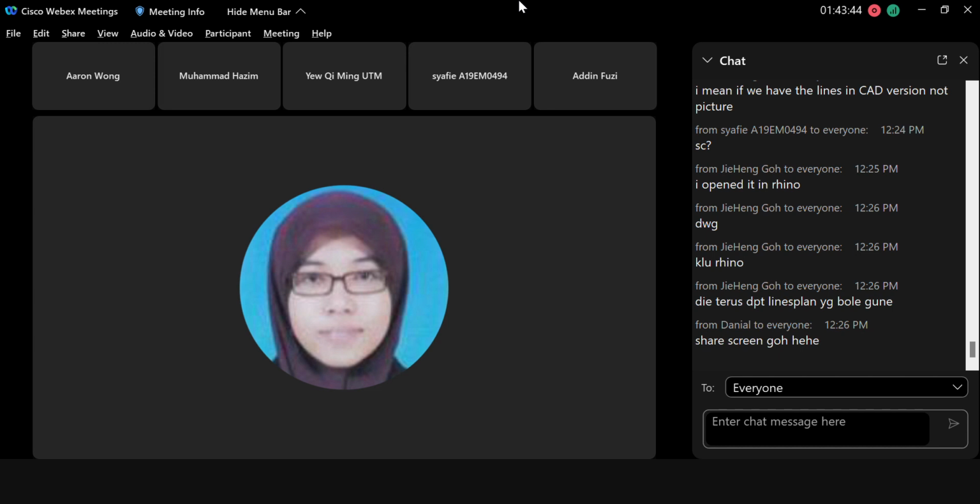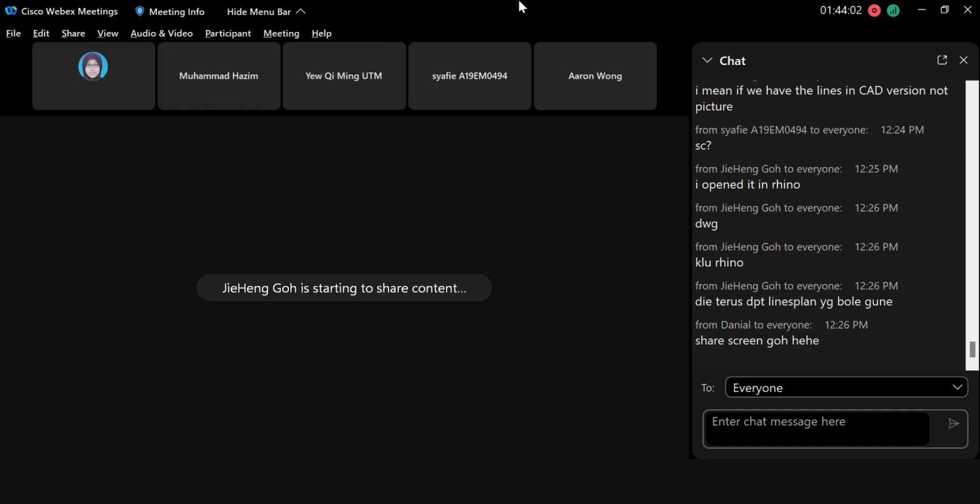I mean, with Maxsurf, you cannot directly put in a drawing. You still have to get the control points. The one that I showed just now with the star, that control point, so that Maxsurf can generate the 3D hull forms. But Rhino, I'm not sure.